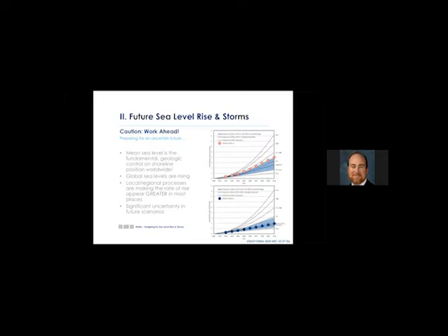But in the context of living shorelines, it's important to keep in mind that mean sea level is the fundamental geologic control of shoreline position worldwide. So you can't really hide from mean sea level, and that is going to dictate ultimately your shoreline position. And also the tidal datums that go about that mean sea level position are going to be important within the context of establishing where some of your habitat is going to be.